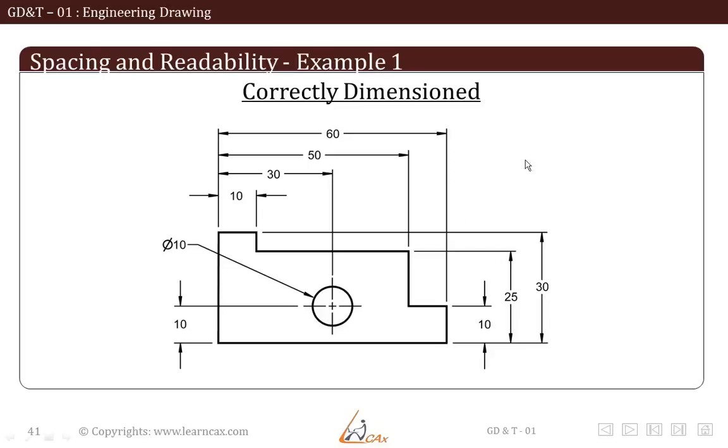One more thing you should notice here is all the arrows are of the same size. Regardless of the length of the dimension line, you should have arrows of the same size everywhere.